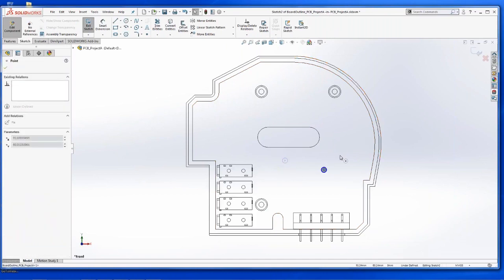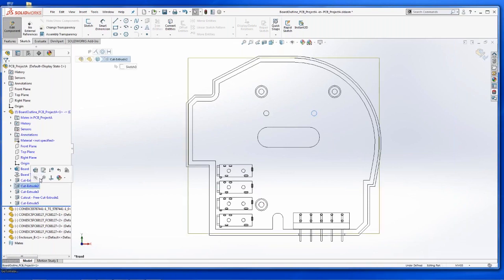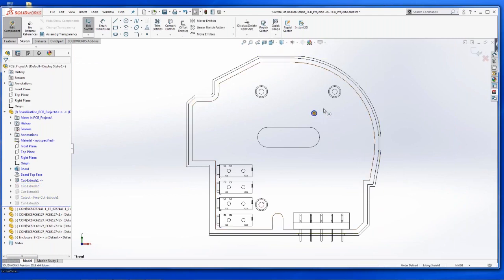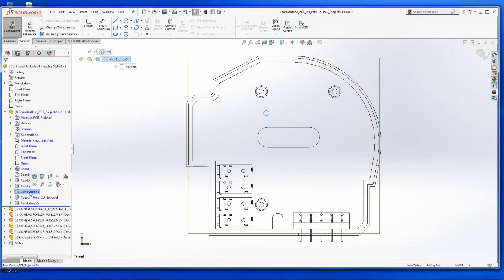Now in SolidWorks, I can drag and drop this anywhere I want. I could create dimensions. I can also change its diameter. If I change that hole diameter in SolidWorks, it will absolutely update the drill value in the PCB tool, because your PCB vendor is going to go off of your NC drill file to drill the board, obviously. So there is a direct correlation between the diameter in SolidWorks and your drill size value in the PCB tool. So let's just drop these other two together, and then we'll push this back.